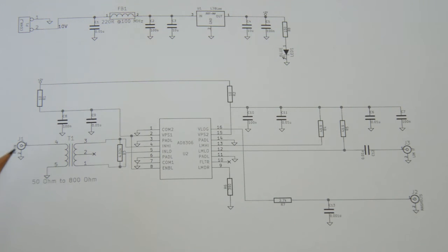The source here has a 50 ohms source impedance, and the chip itself has roughly 1K of input impedance, which means that the impedances are not matched. And actually, in RF design, impedance matching is probably one of the most important topics at all. And I didn't want to sneak this into the back door because I think it deserves some proper discussion. But I don't want to do it right now because honestly, this is not the best example to explain the topics.